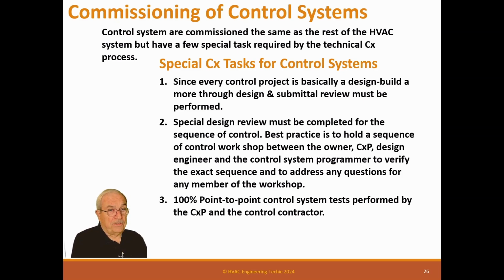Now, a lot of people say, well, that's a waste of money. Why do we do that? Well, because the control contractor said he did a point-to-point, but I bet you he didn't. And having been a control contractor, I understand what happens there. And if you don't actually do a point-to-point test, you're going to end up costing yourself more money, costing the contractor more money, and it will not perform very well, because you're testing more stuff than he does. You're testing point-to-point, and you're testing the calibrations of the sensors.